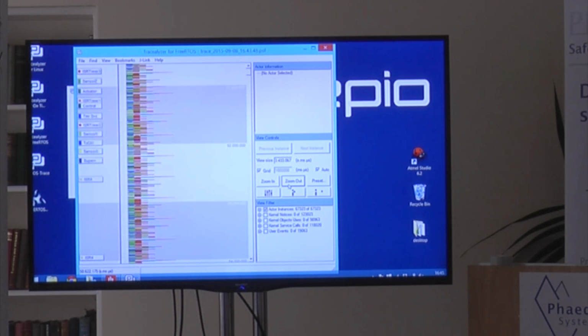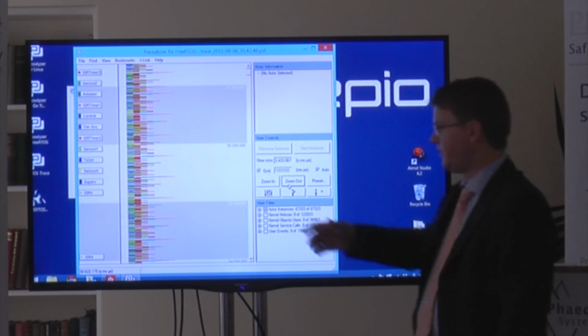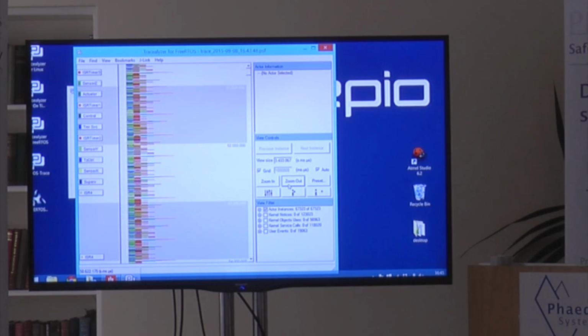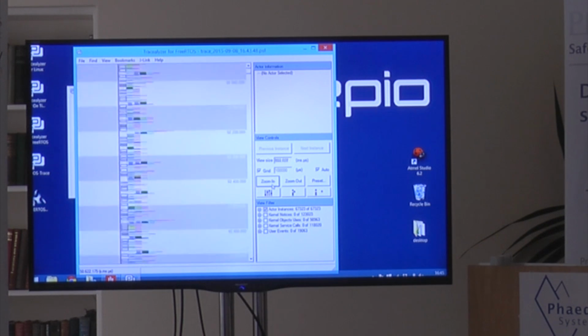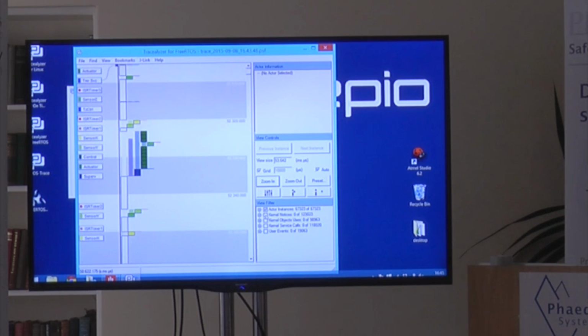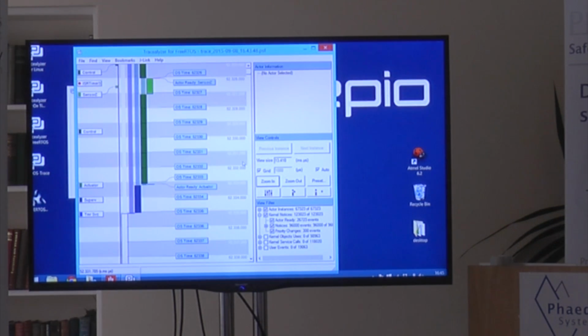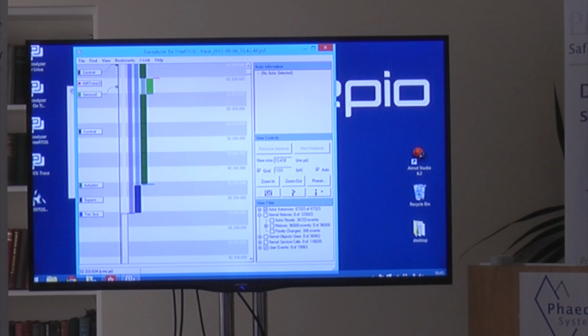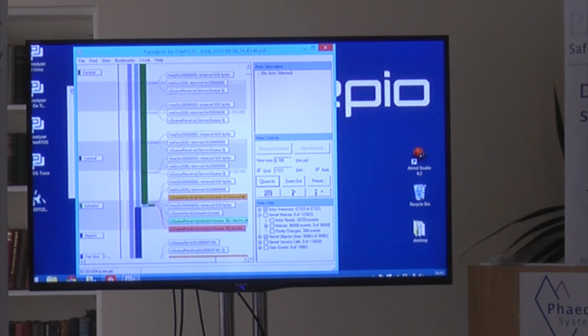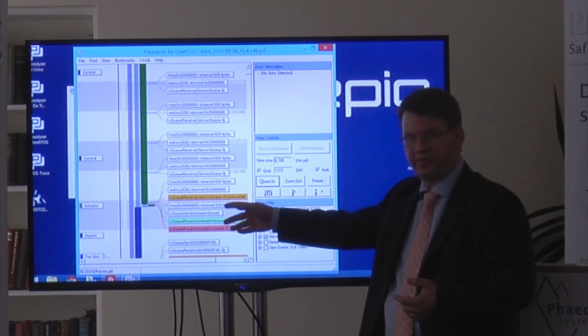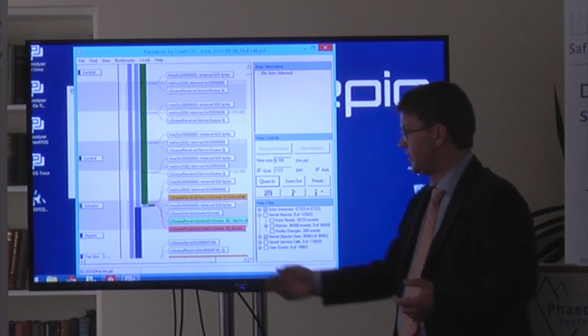Now we are looking at several seconds of execution here, and we can still see these relevant spots where the intensity is higher. And this view is complemented by several other views. But first I would like to show you also all these annotations that we can see. For instance, things like, here we see operating system ticks, but we can also see calls to the FreeRTOS kernel or any RTOS kernel, sending and receiving of messages, memory allocation, etc.